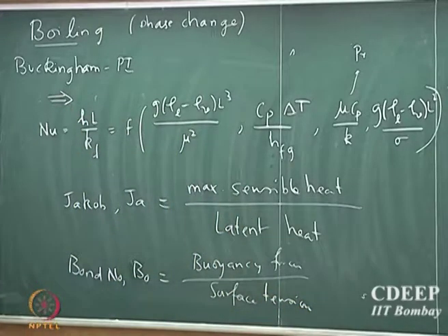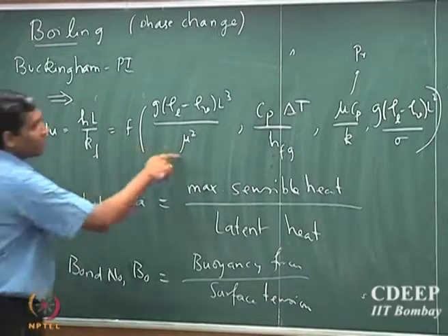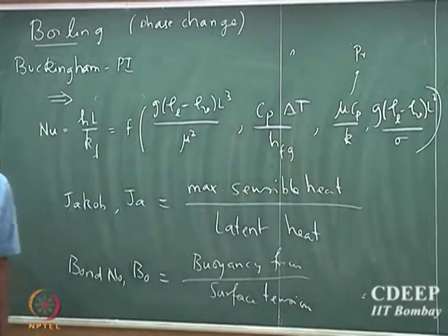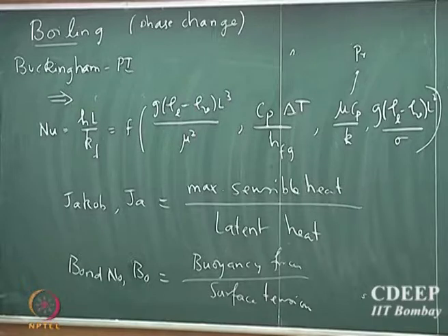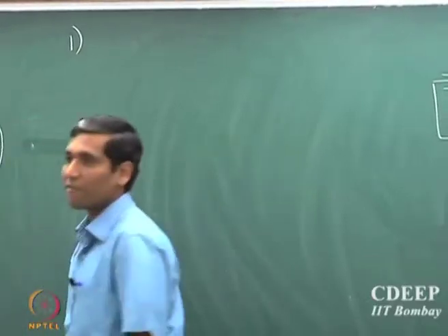So, these are the 5 dimensionless groups that will come out of the Buckingham Pi theorem. I think all of you should try to get these 5 groups. Go back to your fluid mechanics notes where you were taught how to derive these dimensionless groups, and find out what they are, starting from the fact that the heat transport coefficient depends upon these 9 factors here.